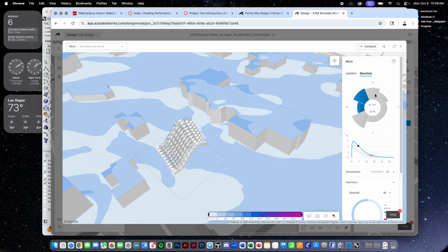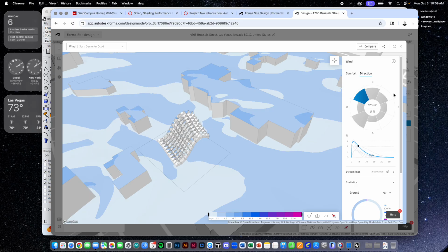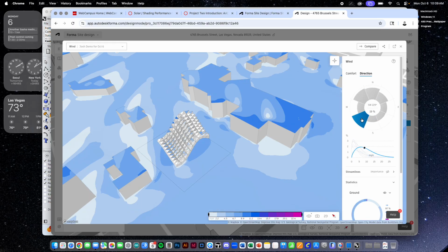So it gives you the wind roses based on our location. You can see, of course, Las Vegas has a lot of north, southwest, some northwest, some northeast. The rest are kind of iffy. They're a real fluke if they come from that direction. And you can start to map, let's say, velocity, and start to understand human comfort a little better.